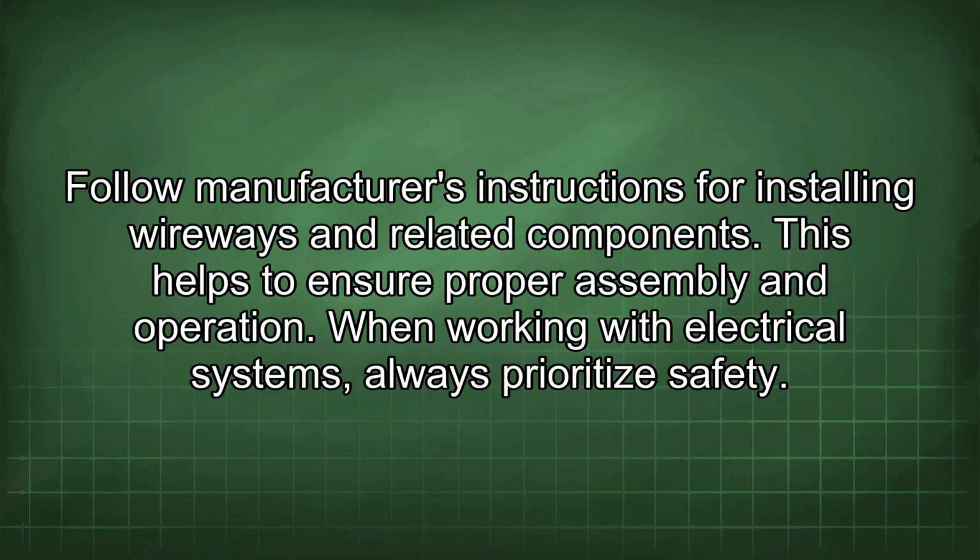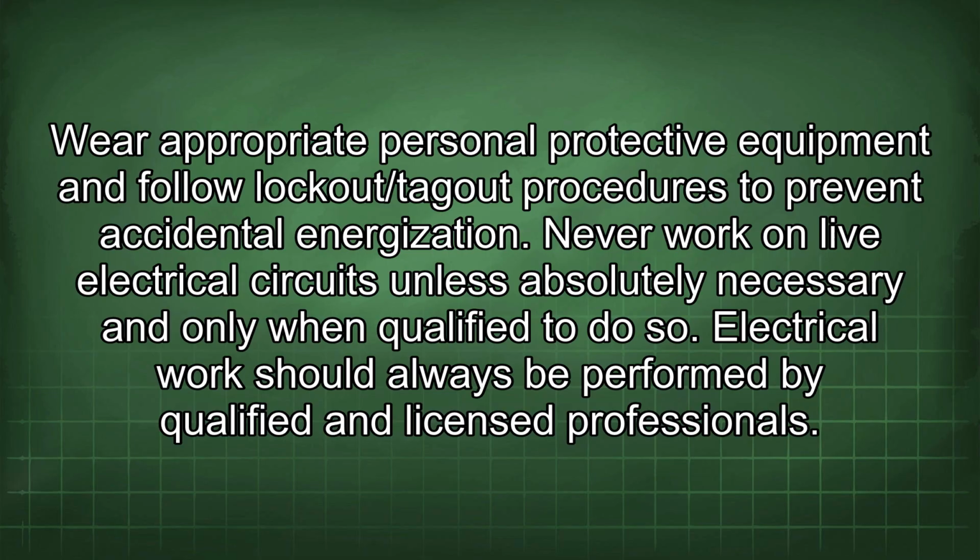Follow manufacturer's instructions for installing wireways and related components. This helps to ensure proper assembly and operation. When working with electrical systems, always prioritize safety. Wear appropriate personal protective equipment and follow lockout/tagout procedures to prevent accidental energization. Never work on live electrical circuits unless absolutely necessary and only when qualified to do so. Electrical work should always be performed by qualified and licensed professionals.